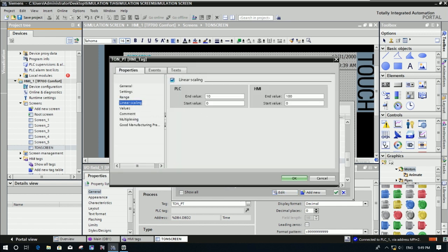So if I would like to set 20 seconds, this one should be 20 and then 20,000, okay. So convert from 20 from HMI and then the PLC will be 20,000 because we use timer on, okay.